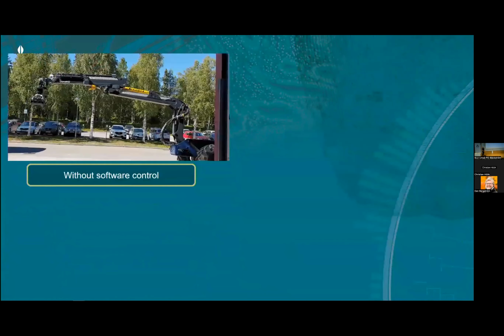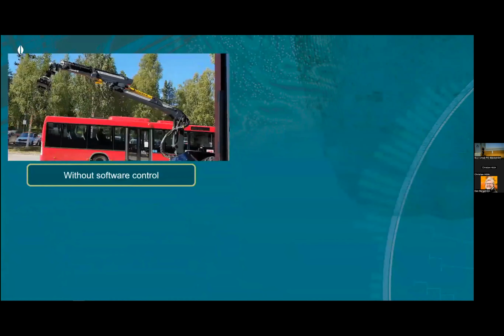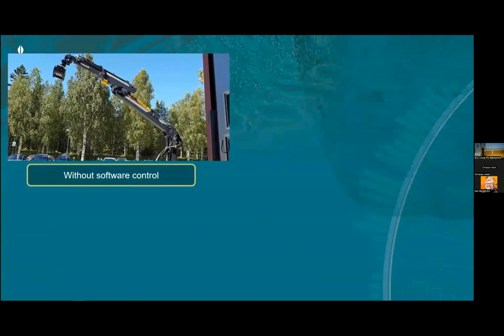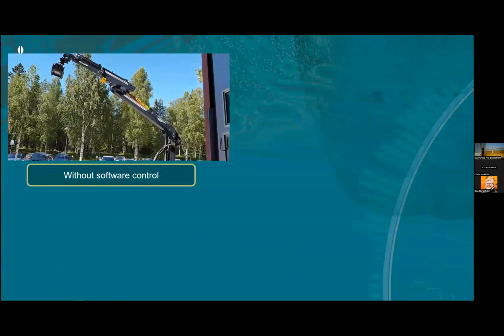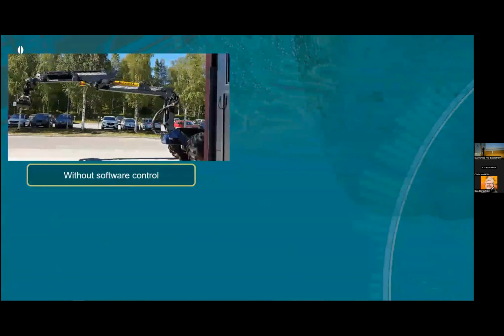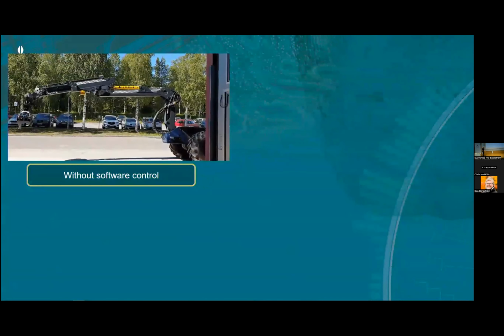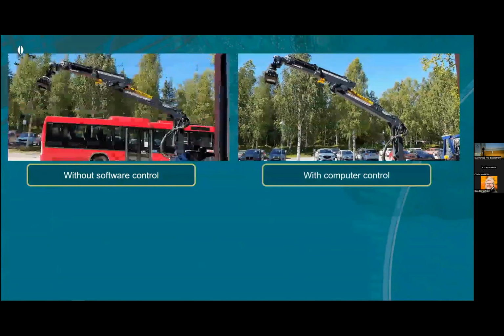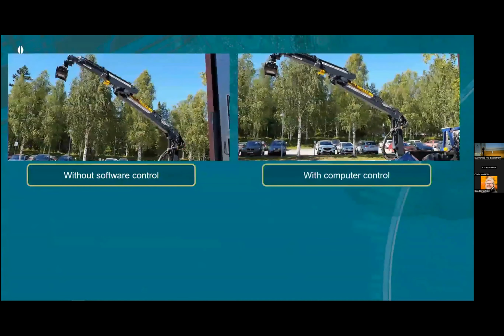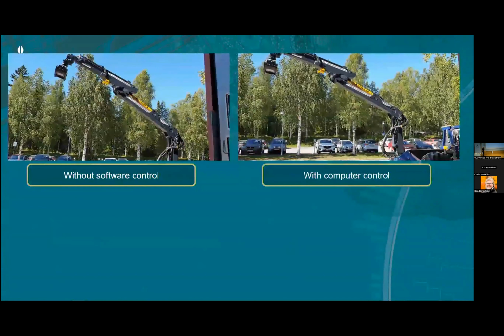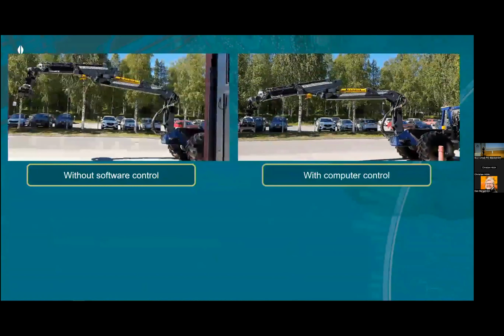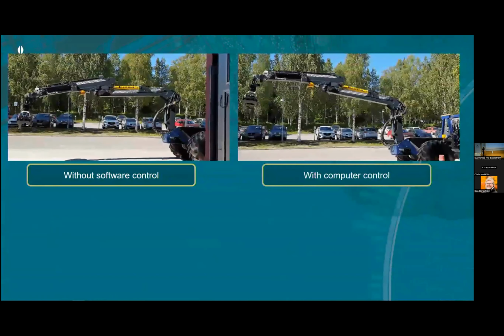In the AURO machine, one of the biggest problems is that when the crane moves, let's say you just let it drop from there, the entire vehicle will oscillate. And it can even tilt forward if you do it with load. The latest versions of this algorithm can learn what the machine is capable of doing. So it completely eliminates any form of oscillation. You can just see it there.